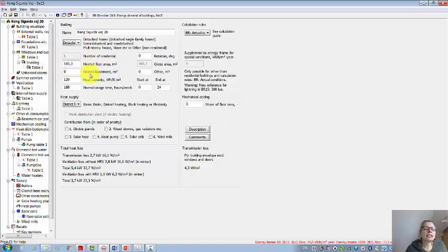The one I'm making the energy frame for here is the same house that we had in first semester, where we did all the U values on. The next part here is the heated floor area, and the heated floor area is all the rooms that are heated. So that means where we have radiators and underfloor heating and all other kinds of heat systems, that's heated floor area. And the heated floor area is calculated as the external area.